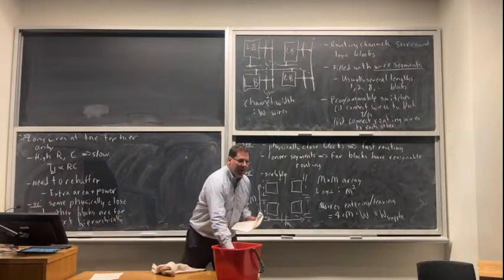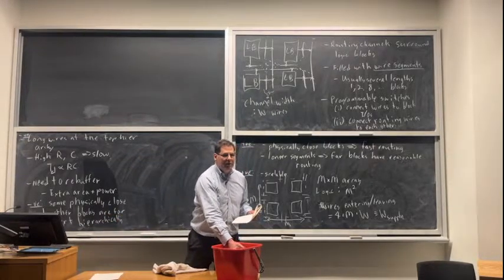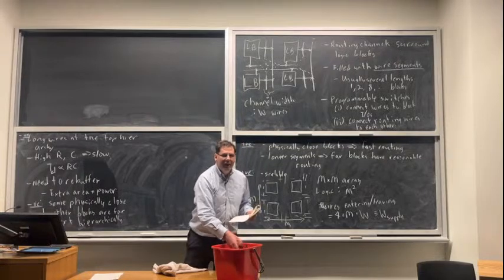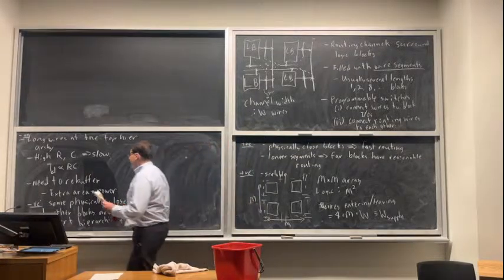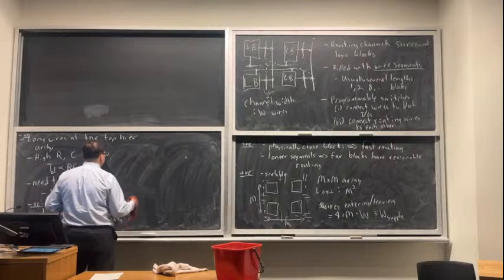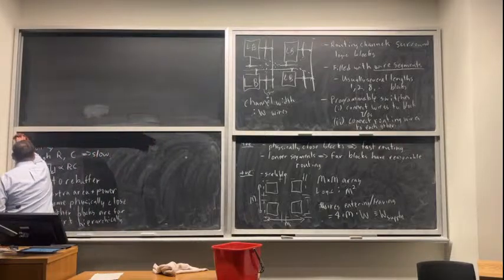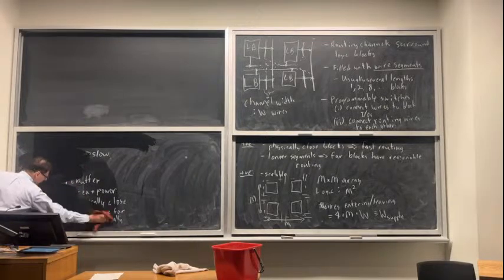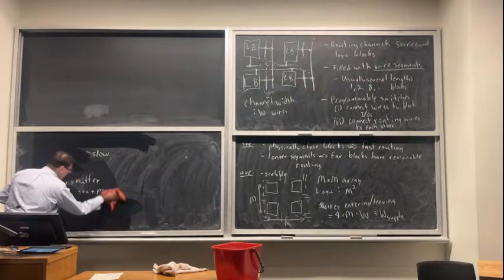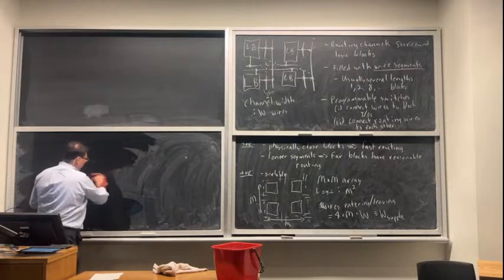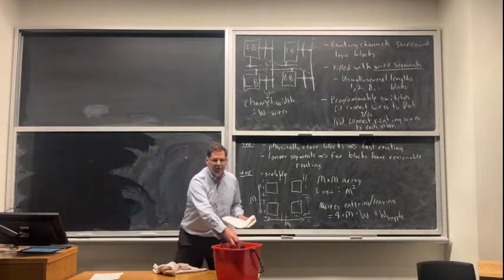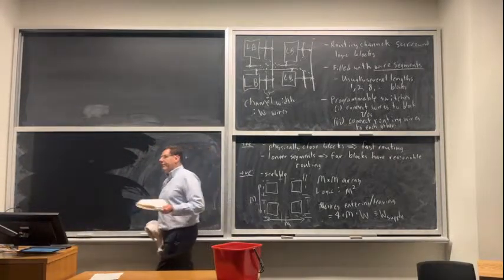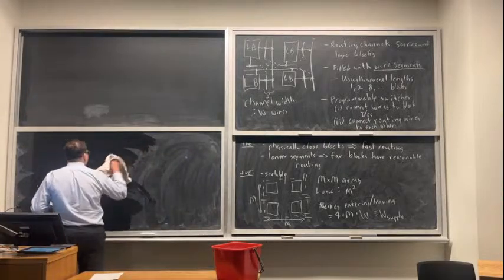In practice, I probably can't use every single one of those wires because there'll be some blockages. I don't have switches that can get at every single one of them independently. So maybe I can only use half of them at any one time. But it doesn't matter for this because this is an asymptotic analysis. It doesn't really matter if you say that in a real circuit, if you try to use every single routing wire, you'll get some blockages and it won't work.